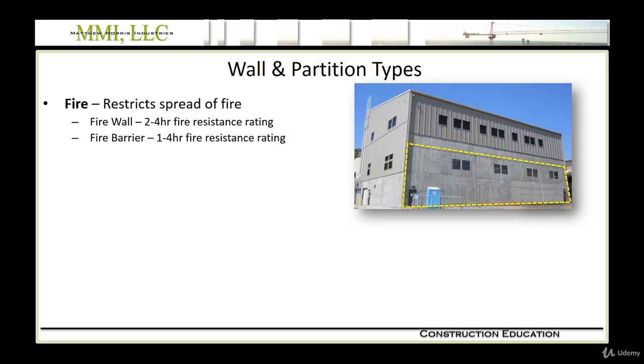We had to build a separation, and that's why we built a 2-hour fire barrier. This was a concrete wall that extended from 36 inches below grade to well over 30 inches above the future roof line of the office, and you can see left to right it extended from exterior wall to exterior wall. You can also see the windows were left in place.